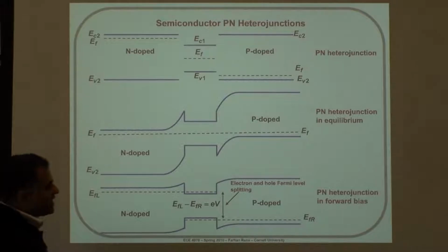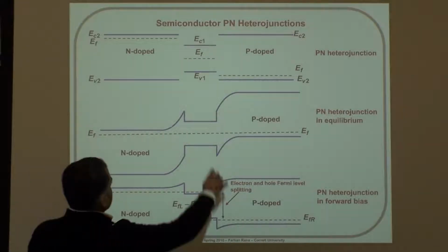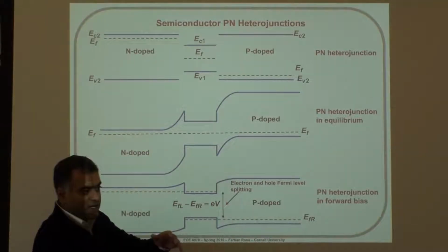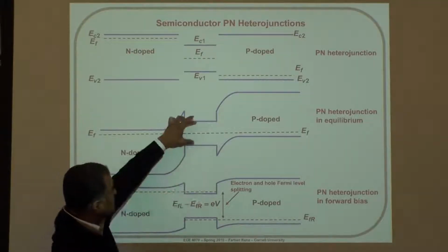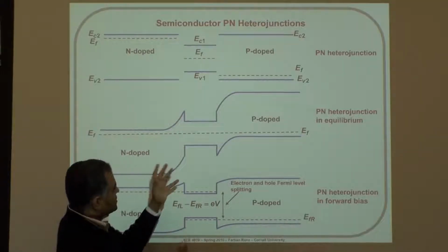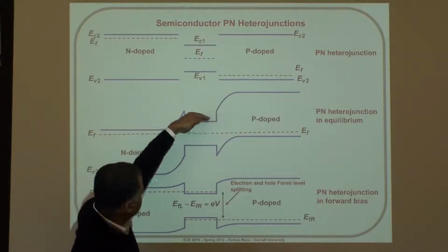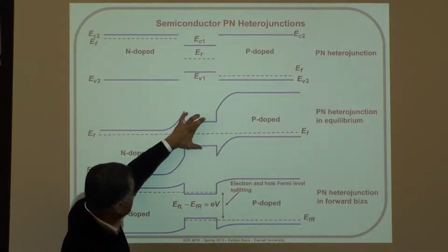The way this is realized in a real semiconductor nanostructure is you have your quantum well. You have designed your states here, chosen your wavelength by designing the quantum well thickness and all that, right? Material choice and the thickness of the quantum well will let you design the exact wavelength of light, right? And let's say you go from the ground state here to the ground state here, but then to